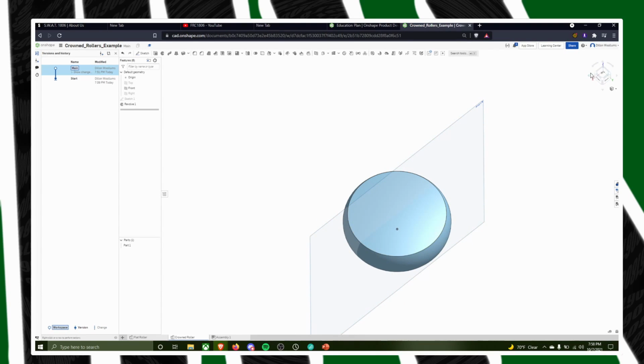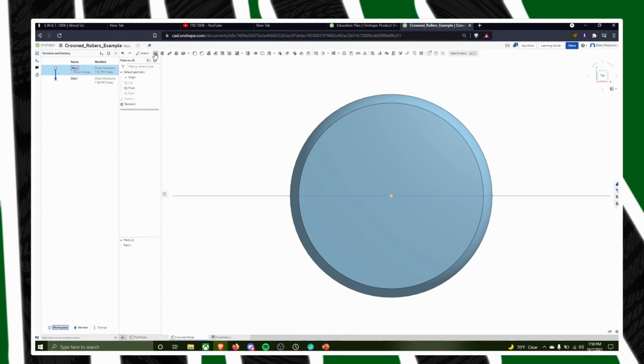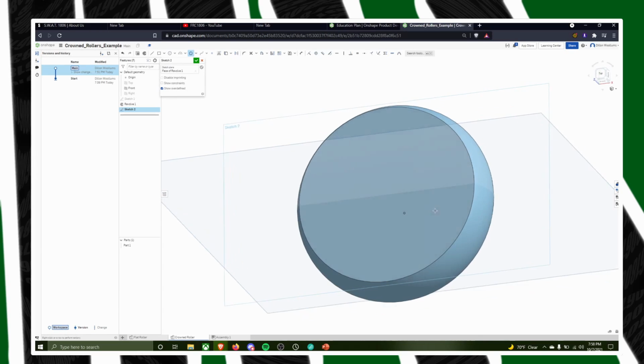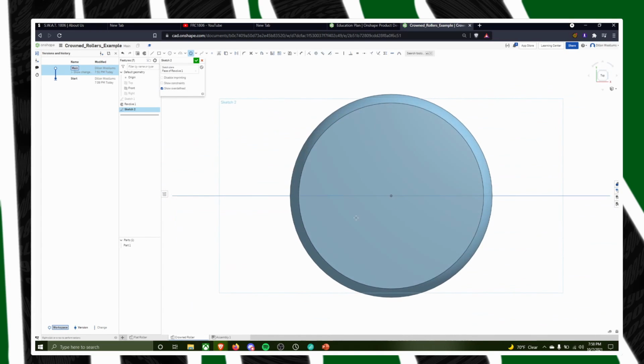That's great. But now I need to go to the top, hit sketch, and then you can actually just select a face on your object. We need our friend the inscribed polygon again. And then make sure you're centered on the top view. So you can use this point. Click out here again. Want 6 sides and dimension that 0.5.